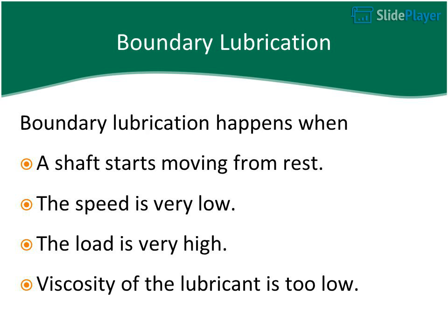Boundary lubrication happens when a shaft starts moving from rest. The speed is very low. The load is very high. The viscosity of the lubricant is too low.